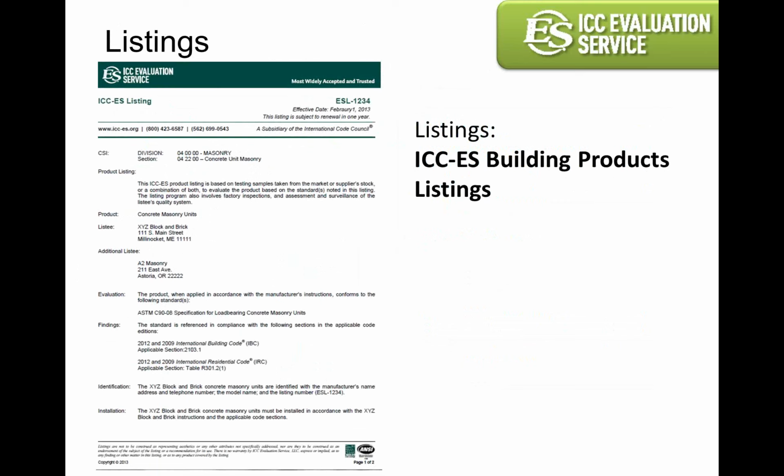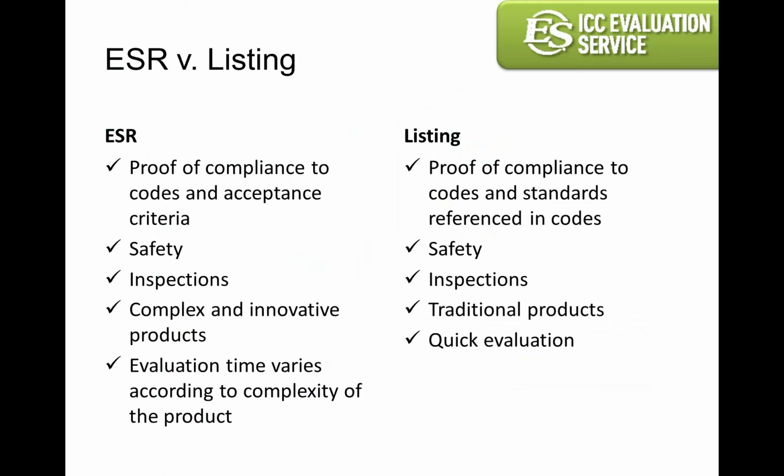So in the example here on the screen, this particular brand of CMU meets the strength requirements of the code. Exactly, and material requirements as well. Within ASTM C90, there's a list of requirements that CMUs have to meet, and this would show that they meet those requirements. And also have the quality control as well.